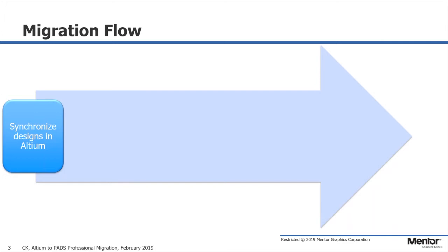So that's step one. After that, we're going to create a design-specific central library. We'll start with an empty library, and then as we translate our design, we're going to bring over all of our schematic symbols, our cells, pad stacks, and parts into this design-specific central library.